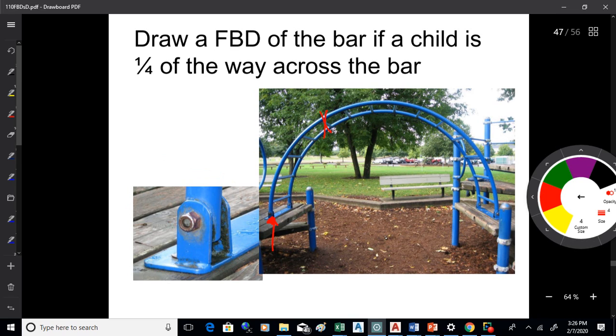So up we go, like that. Will the pin joint allow motion left and right? It won't. So there has to be a force to prevent motion. Forces prevent motion, okay? Will one pin joint allow that thing to rotate? Yes, it will. So there's no moment reaction on a pin joint. There's two forces, perpendicular.